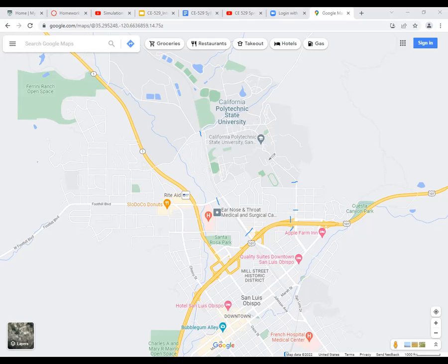So I'm just trying to ask you to think about, if you knew certain counts at certain locations, how are they useful? I mean, obviously for the purposes of answering the question for this lab, traffic counts is a good answer. I will accept that. That's a perfectly fine answer, that yes, you need traffic counts. But let's say you have these traffic counts here. How does that help you build the model? Yes. So you can sort of see the inflow and outflow of traffic in different areas. Right. You can identify those congestion areas, and that can help you validate the model, if your model is doing a good job or not.